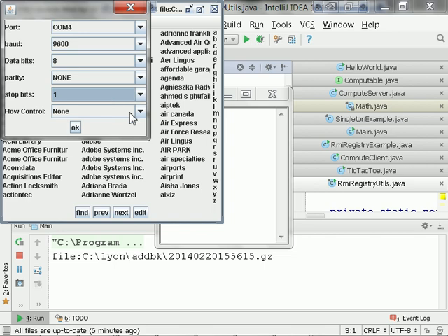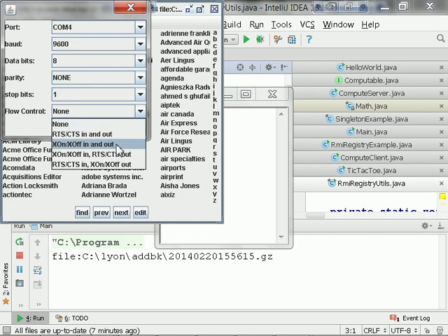And then there is either software flow control or hardware flow control. Isn't RS-232 wonderful that it gives you all these choices? And as a Java programmer, flow control is done with Control S and Control Q, or X on, X off. These are the RS-232 ASCII symbols for determining when to turn off the transmitter because you're being overwhelmed, and to tell it, slow down, I can't keep up. If you're a little 8-bit toaster controller like an Arduino, that could be really useful, especially if you're being swamped by some high-speed baud rate coming in.